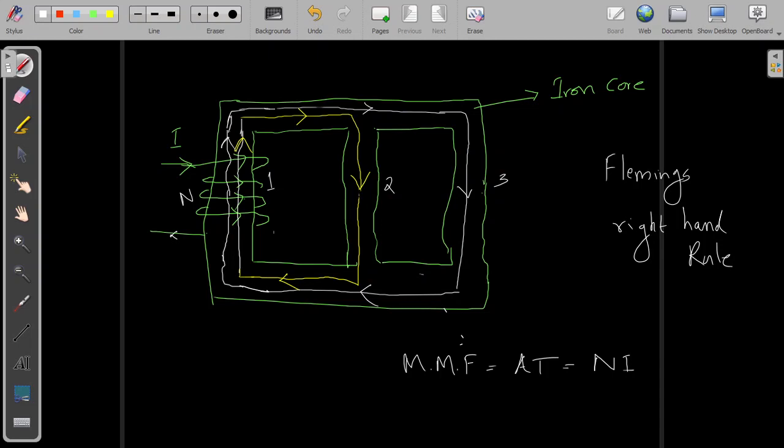In an electrical circuit, the fluxes are analogous to the current. Flow of flux means flow of current. So current is flowing in two paths, which means the current got divided into two paths, which means the two paths must be connected in parallel like this, right?